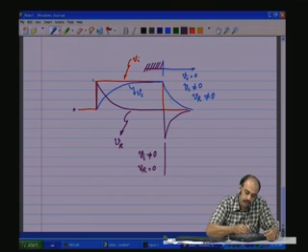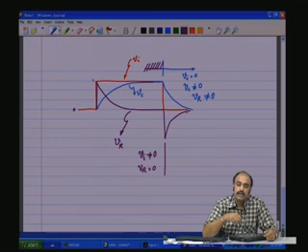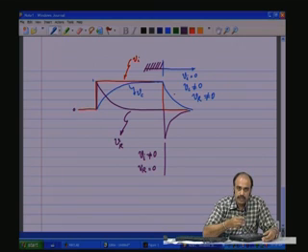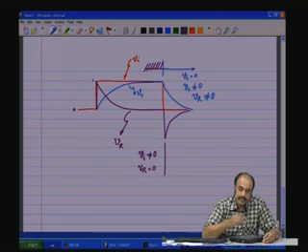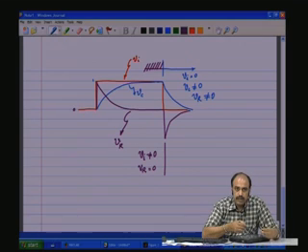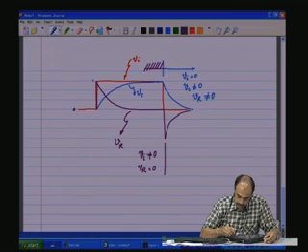Vi is made 0, but the vehicle speed is coasting, gradually decaying to 0, which means the output is there even though the input is 0, that is the existence of the pole, and the decay depends upon the position of the pole in the S plane. Likewise, for the zeros, if any particular variable decays to 0 like a differentiator, then there is the existence of a 0. Okay. So, this concept you should get it clear.